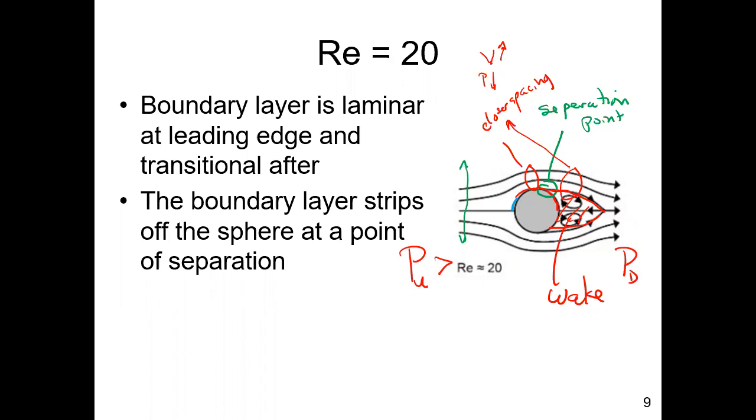And if you take a slice through this and look at the sphere as a circle, I think a long time ago on Faraway Place, we talked about forces on plane submerged objects. In this case, you have a circle with one pressure on one side and one pressure on the other. The pressure upstream is greater than the pressure downstream.